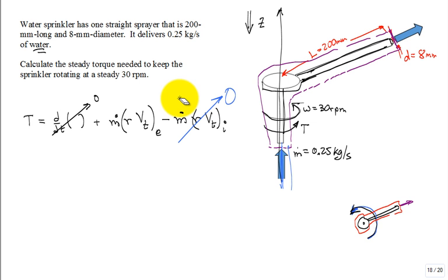Now we take a look at the outgoing. Maybe it's good from this top-down perspective. The fluid leaves the end of that nozzle, and it's just a straight shot out, radially out. True? Okay. Well, what is R? R looks to be like 200 millimeters. But what is V tangential? Well, we already know the mass flow rate. That's 20.25 kilograms per second. But what's V tangential?